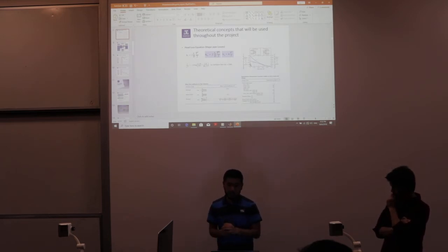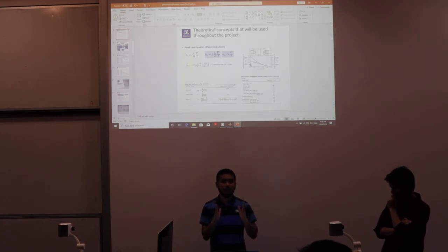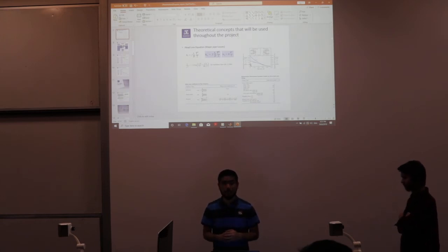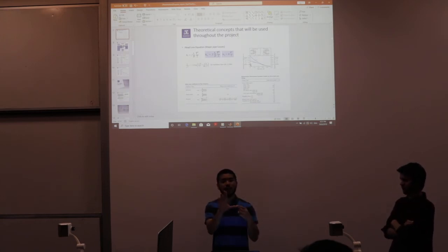It's good actually. So what we did was we tried to square the edges of the pipe ourselves. We did it with the CNC miller. So we milled the ends square, so the edge of one pipe can connect to the edge of another pipe at pretty much 90 degrees to itself. The key thing is trying to keep that in place.